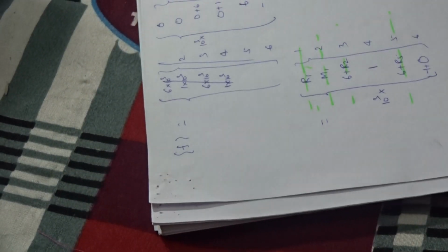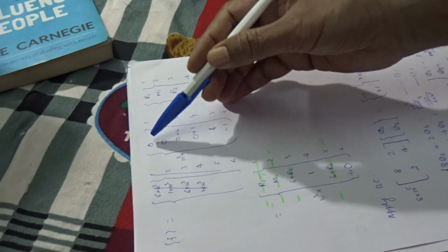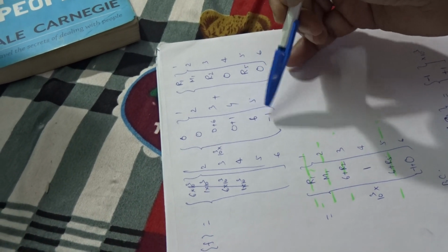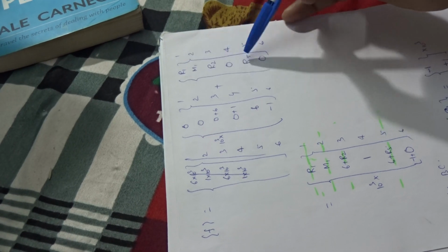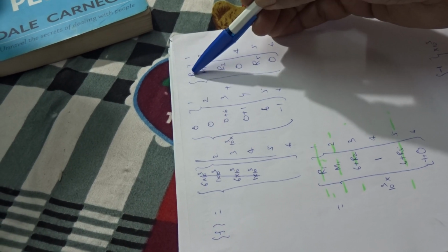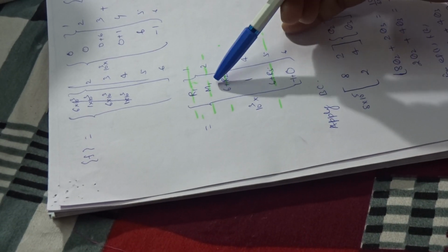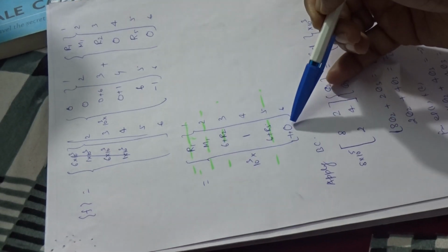And this is the final force matrix. For the distributed load, for element 1 it is 0 0 0 0. For element 2 it is 6, 1, 6, minus 1, with 10 to the power 3 common, plus the force matrix due to the point loading, that is, the reactions and moment. So the reactions are R1, M1, R2, 0 and R5, 0. So the final force matrix is R1, M1, 6 plus R2, 1, 6 plus R5, and minus 1, plus 0.